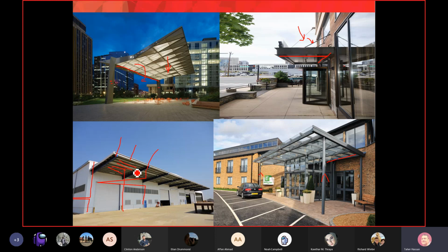If I reversed those joists, so my joists would go this way, perpendicular to the building, I would say there must be something in between the columns, like a beam, and it will do the same thing as here. You know what?